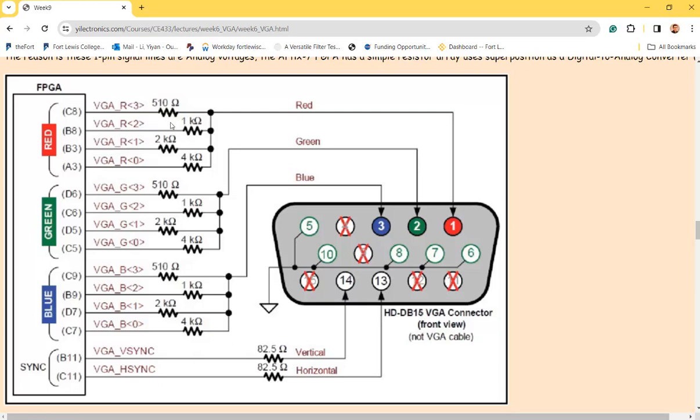Should we have a quiz on superposition? You will have a few quizzes on superposition in digital next year, so it's good to understand what's going on. Basically, if you have a 1 here, you ground all the other sources, and then you calculate the voltage contribution from that source independently. So you are looking at individual contributions to the same node. Eventually they add up, or are superimposed on each other, to form an analog voltage.